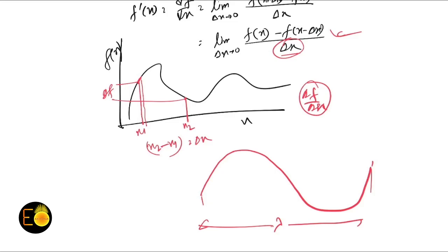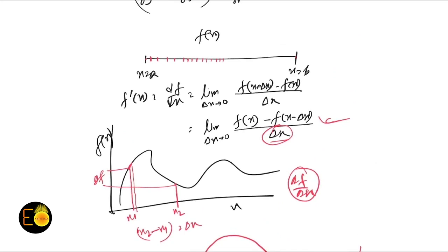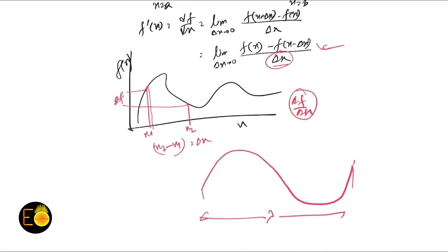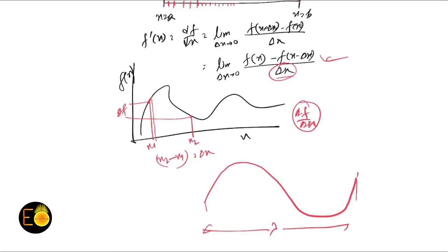Now you have to choose these grid points. When we're doing the simulations, we call them grid points. We have to make these grid points in such a manner that the minimum criterion is at least 10 grid points per wavelength. So from there to there should be 10 grid points. The smaller the grid point you consider, the more accurate your results will be. But here during this simulation we will see that even 2000 grid points I will consider for two-dimensional simulation.